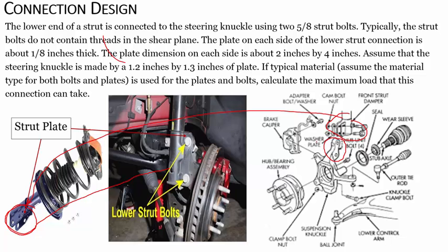The type of failure you can have in this case: this strut bolt might get sheared off. Number one, if the bolt is weaker, it can fail because of the weak bolts. The bolt is sheared off by the plate. Number two, maybe the bolt is strong, but these strut plates may be sheared off, cut off by the bolt.